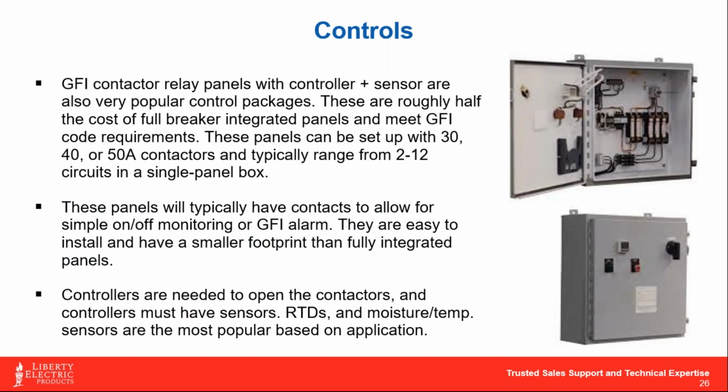When we talk about contactor relay panels, we touched on it a second ago. These are very affordable, usually a standard bearer on a lot of systems because they're pretty low cost, but your labor units go up. You've got to bring over each circuit to the contactor relay panel. Now the contactor relays can also take care of your GFI code requirement. They will need a signal to close the contactor. So generally with a contactor relay panel, you are going to have a controller and a temperature sensor, depending on who the manufacturer is.